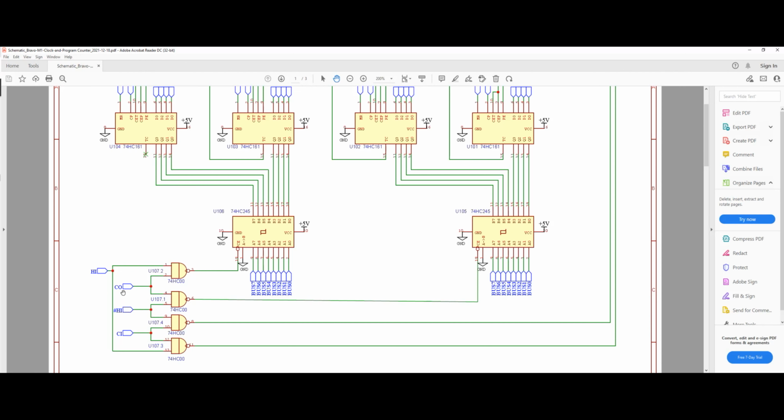If we bring the counter out high, then we have 1s on both inputs of that NAND gate, and therefore we're going to have a low signal on the output, which means that we are enabling the low byte output. So by default, when we turn on the computer and we want to do the output, if we just bring up the counter out signal, we are actually outputting the low byte.